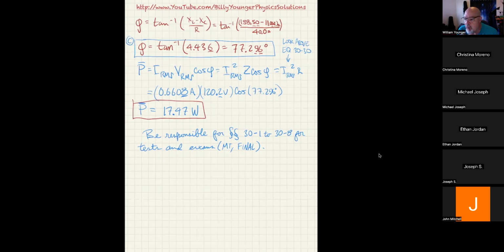Similarly, you could run a wire through an inductor and then to ground between the stereo and the actual tweeter. As the input signal comes out of the back of the stereo, you would continue that wire straight on to the tweeter, but you would branch that wire off and send a certain amount of that voltage through the inductor to ground. And what that would do is force all the low frequency stuff to run to ground, so you'd only get the highest frequency stuff coming to your tweeter, which is, again, what you want from your tweeter. So any questions on that?